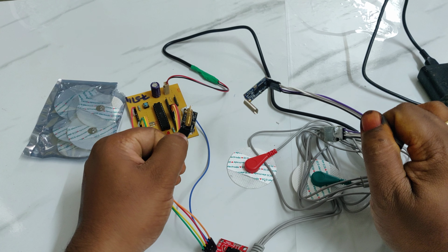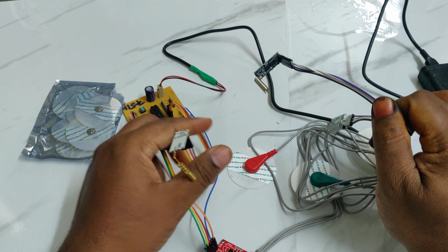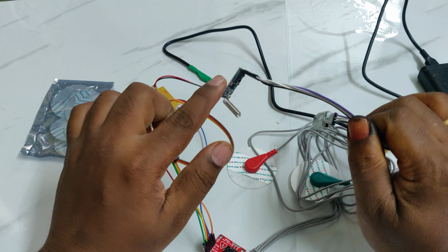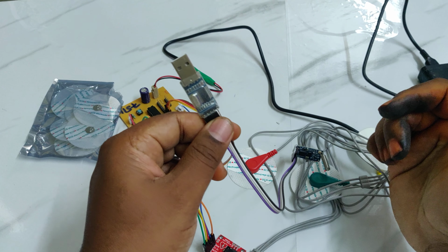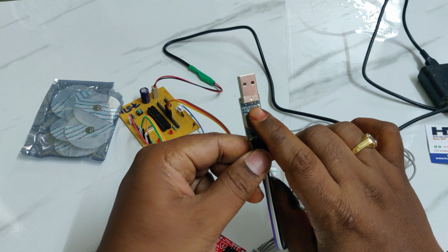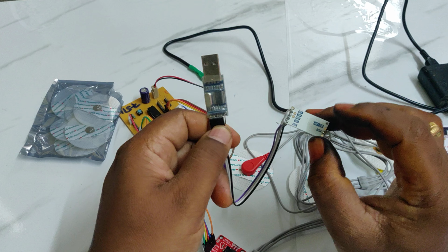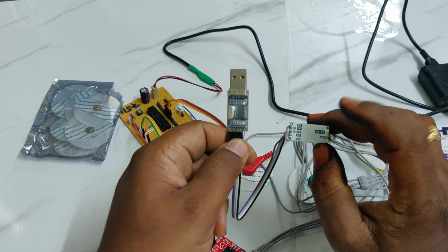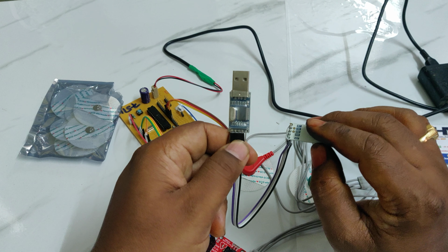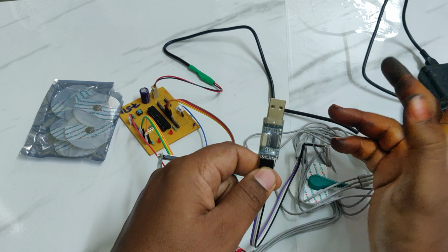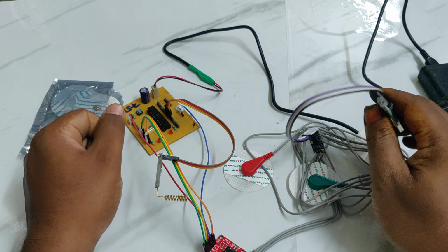So these are the two wireless communication modules, Zigbee, we are using here, and that was interfaced at pin number B0, B1. The received signal will be given as input to the laptop through this USB to TTL converter, which is mainly used to convert the TTL data, transistor-transistor logic, received from this Zigbee module, and that will be converted to USB data as the MATLAB laptop can read the USB data directly.